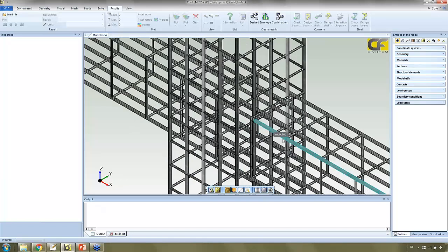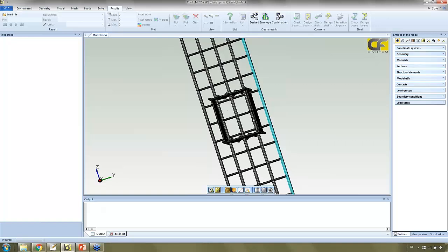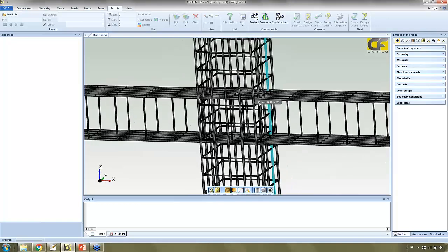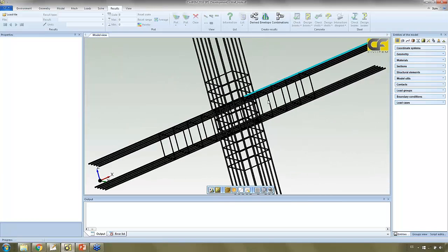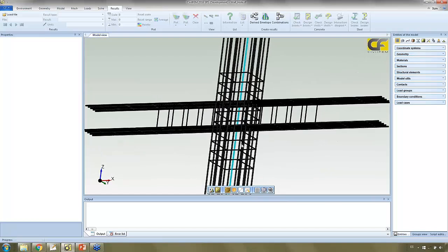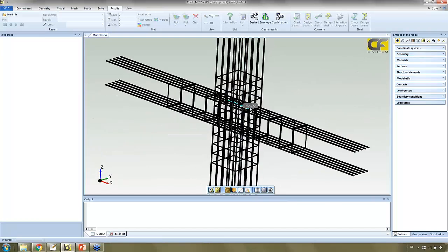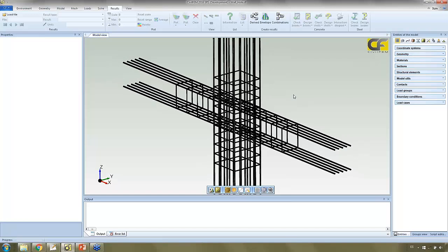We have different straight bars and straight stirrups in the two directions, one for the beams that goes inside the column, and this is the configuration. In this, I didn't add any special reinforcement for seismic behavior, but we could improve it if we need to get a better ductile behavior of this union.